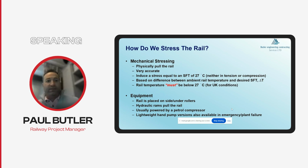So mechanical stressing, this is where we physically pull the rail. So we will grab it in 2 clamps and pull the rail together to a predetermined set of dimensions. So we're looking to induce stress equal to a stress-free temperature of 27, or whatever the limit is within your local area around the world. And the way the calculations work, it's based on the difference between the ambient rail temperature at the time of the operation and the desired stress-free temperature, which is classed as delta T.